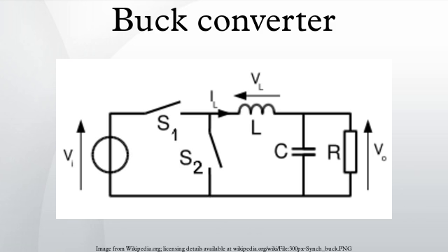Concept. The conceptual model of the buck converter is best understood in terms of the relation between current and voltage of the inductor. Beginning with the switch open, the current in the circuit is zero. When the switch is first closed, the current will begin to increase, and the inductor will produce an opposing voltage across its terminals in response to the changing current. This voltage drop counteracts the voltage of the source and therefore reduces the net voltage across the load.